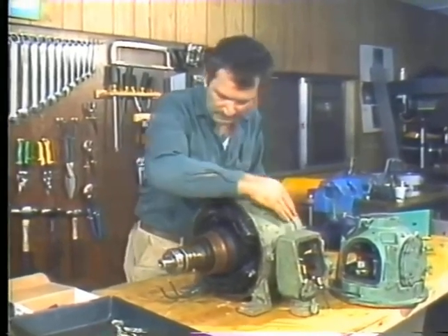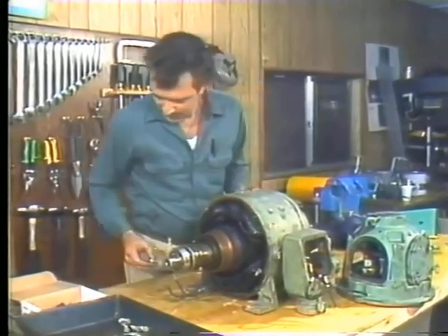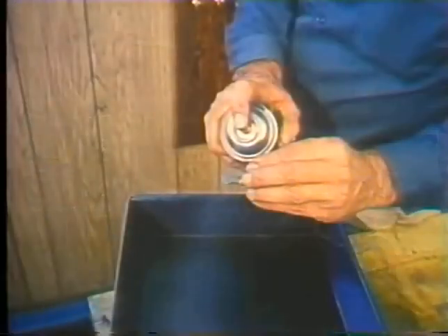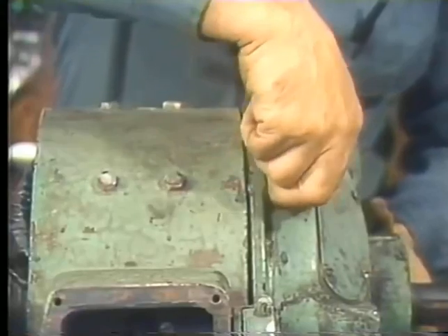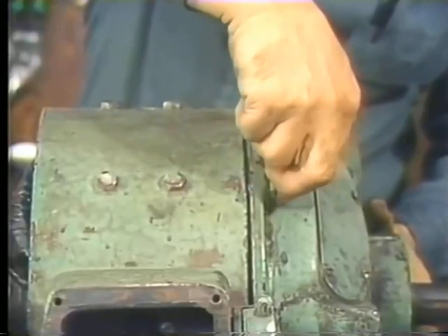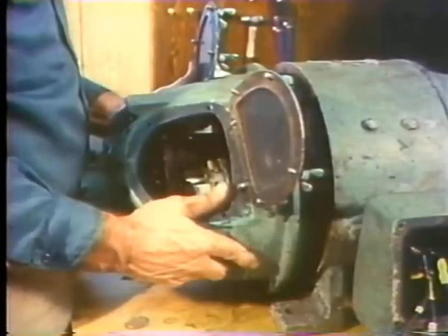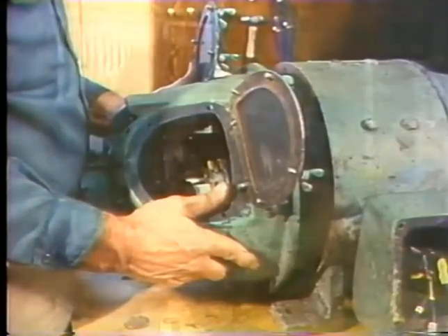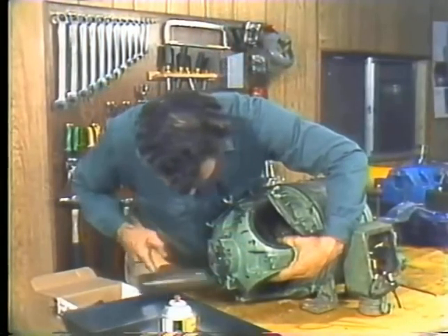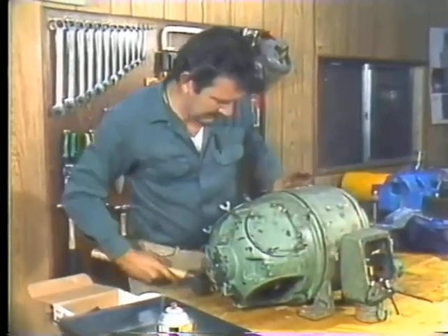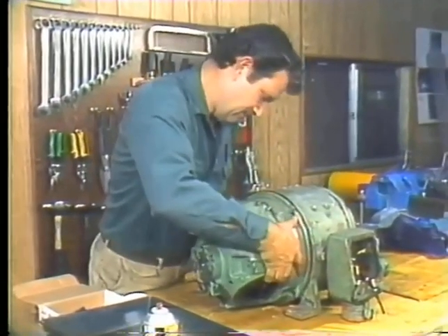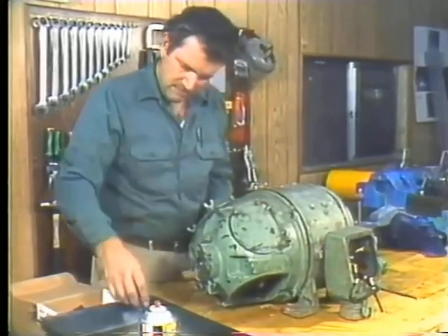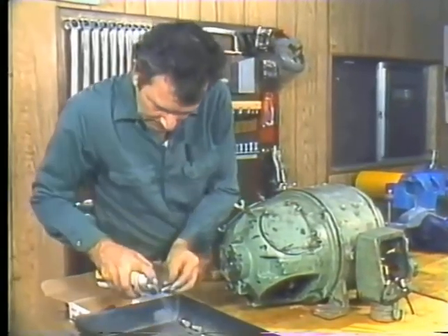Before you line up the punch marks and start the end bell bolts, lubricate the bolt threads. Don't tighten the bolts yet, just start them so the end bell won't slip off the bearing. Then replace the other end bell. Be careful not to let the brush rigging hit the commutator. Use your soft hammer to tap the end bell on the bearing after you've lined it up. It won't go on all the way until you've lined the machine surface up with the frame.